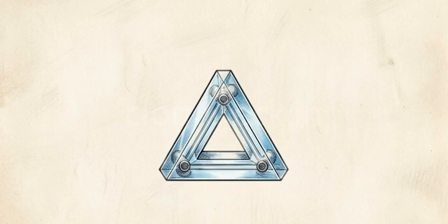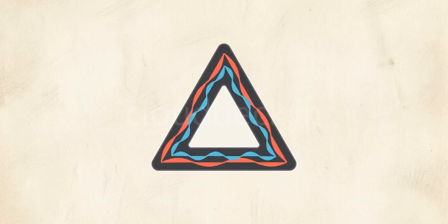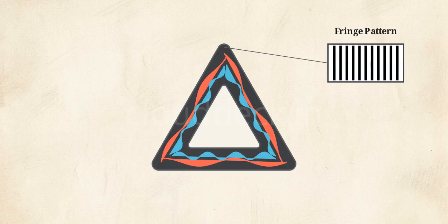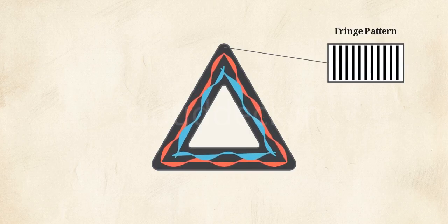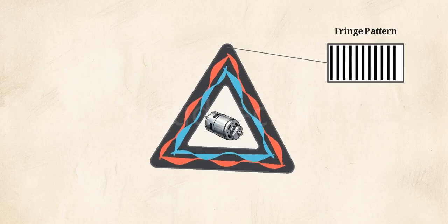It replaces mechanical spinning metal with trapped light. Inside an optical cavity, two laser beams travel in opposite directions around a sealed triangle. When the aircraft rotates even a fraction of a degree, the path length for one beam slightly increases while the other decreases. The laser waves shift out of phase, creating an interference fringe pattern that measures movement with extreme microscopic precision. At very low rotation speeds, the frequencies of the two lasers try to lock together. To prevent this, a mechanical dither motor rapidly vibrates the sensor block, forcing the lasers to remain independent.